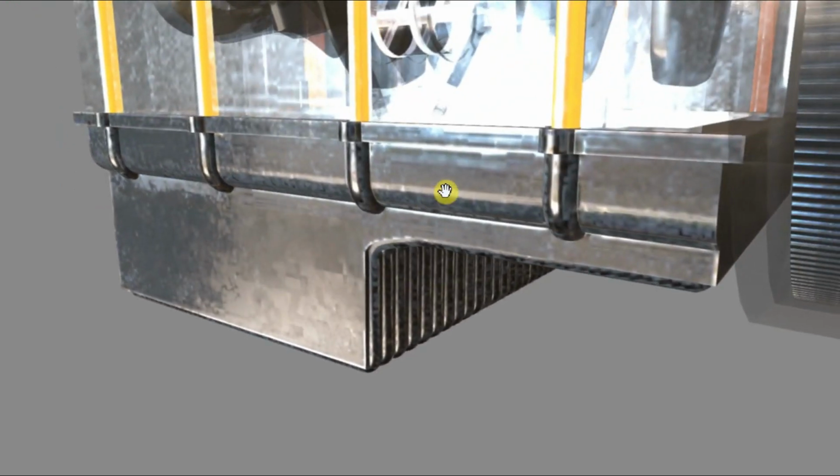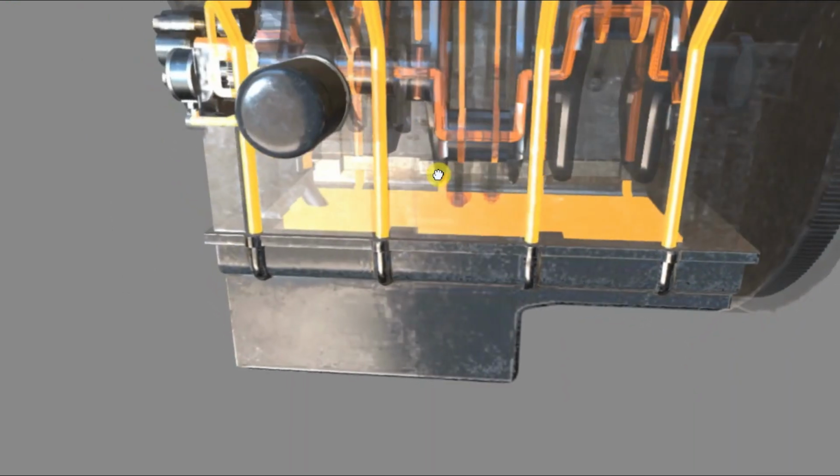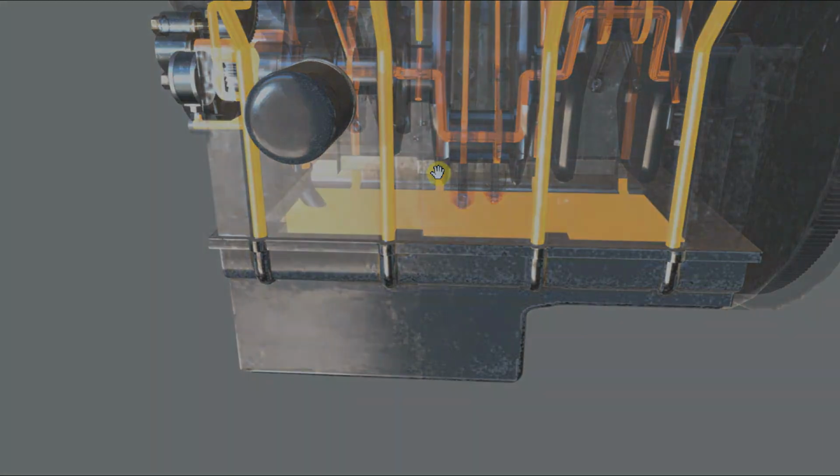When you start looking at larger sized engines, you won't rely on air to cool down the oil any longer. The heat generated by the engine is simply too much, there's too much oil to cool down, and it's not efficient any longer to cool the oil using air. So what you'll use is an alternative system such as water.